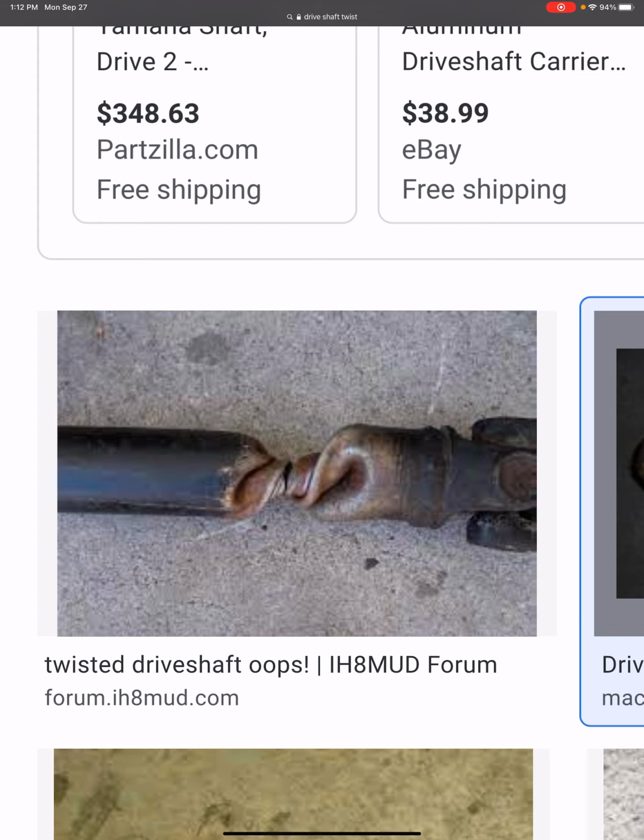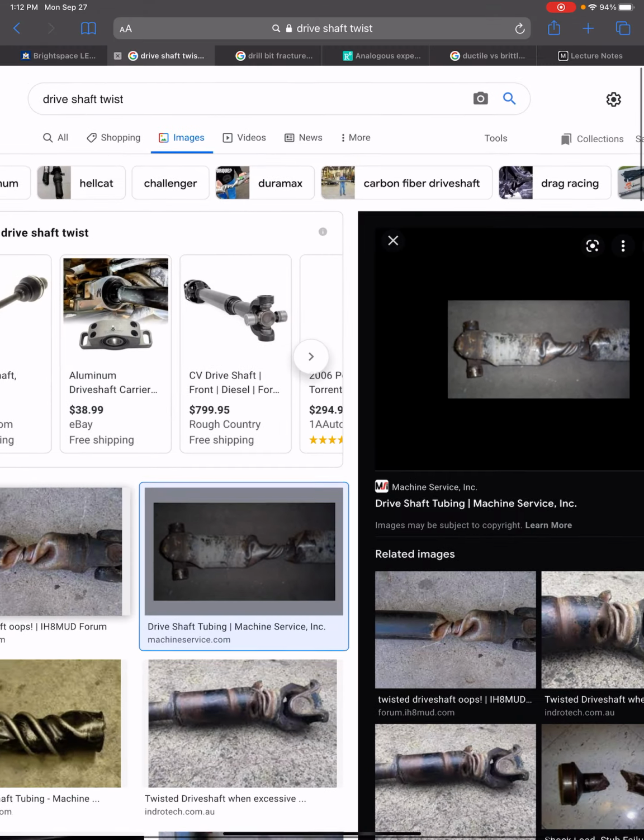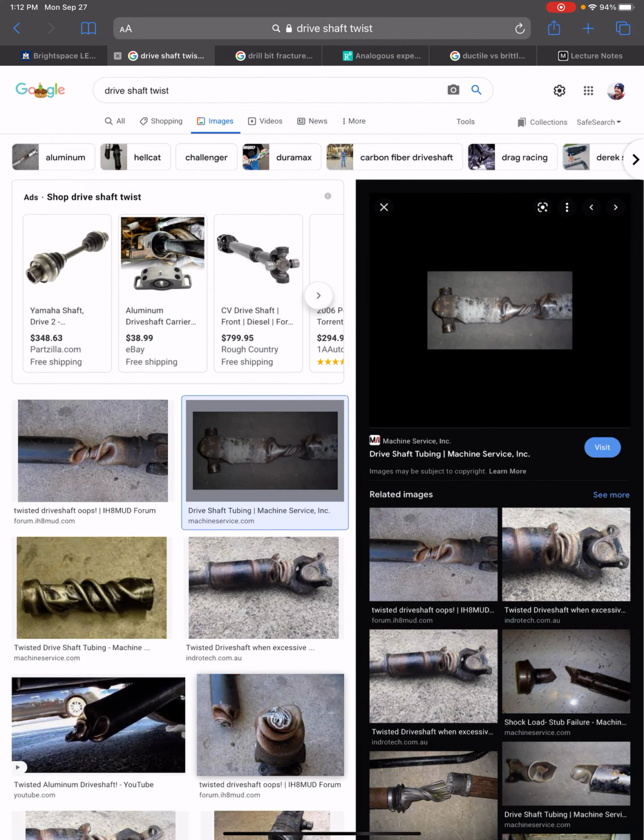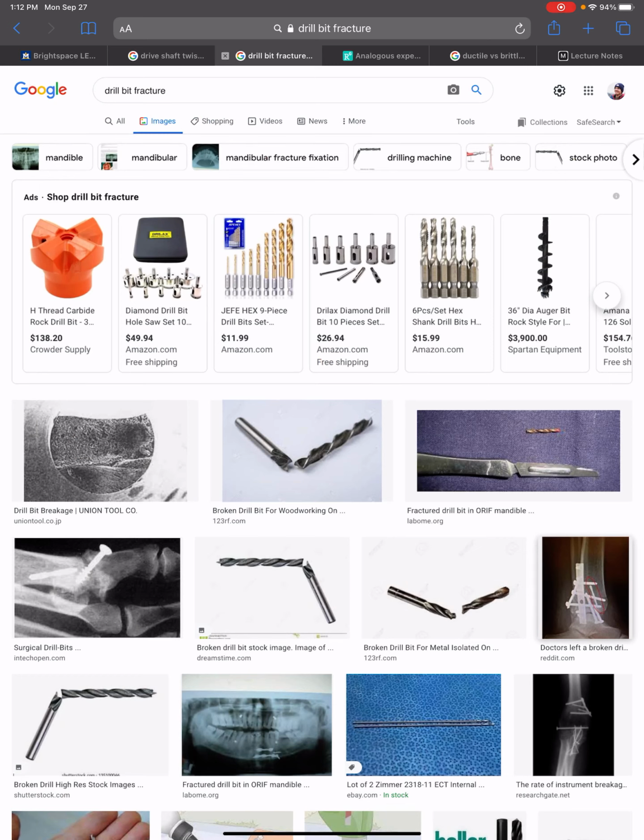And so what will happen is, because drive shafts are very large diameter with thin cross sections, right? Because they're very good and efficient at transferring torque. But the unfortunate part about that is it can get so thin that it's unstable with respect to buckling. So it's going to be trying to pull it apart in one direction, but then it's actually trying to push it together. And the drive shaft will buckle and it'll start twisting like this. And we'll get into that when we talk about Mohr's circle and transposing stresses and stresses at different planes.